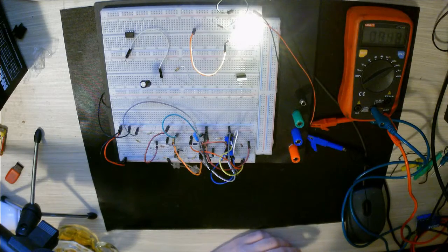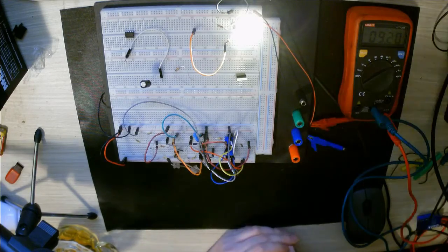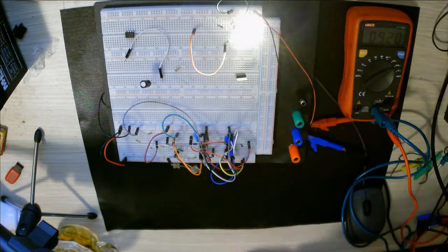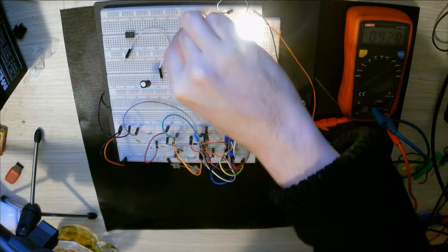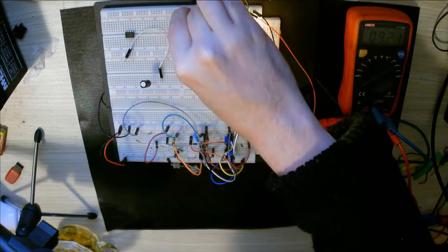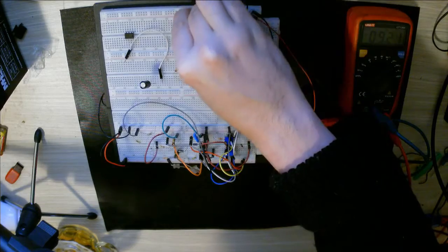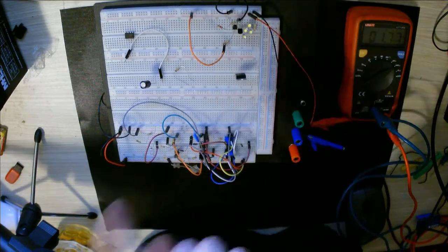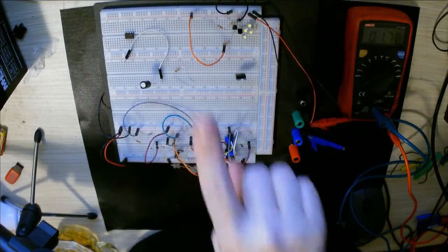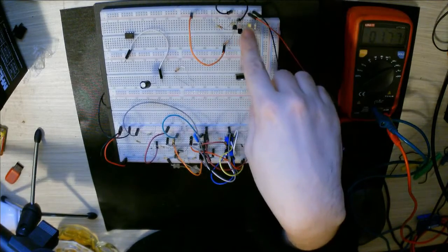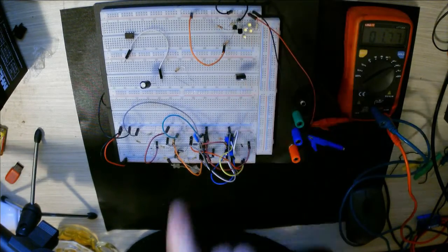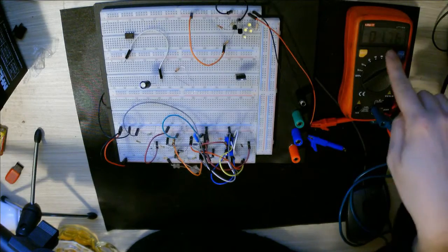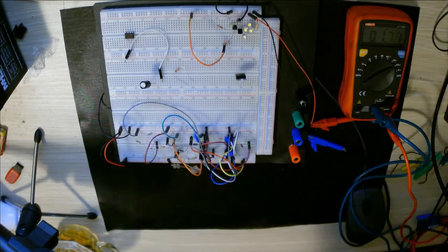11 milliamps. Let's just go down. Okay, I'm at 13.8 volts. You'll have to trust me. 9 milliamps. It's relatively bright. It's ambient light. No need to drive them too hard. If I connect this connector, should give you a better view of my circuit, which is exactly as I've drawn. You'll notice that the LEDs go out, and the current drops to 1 milliamp.